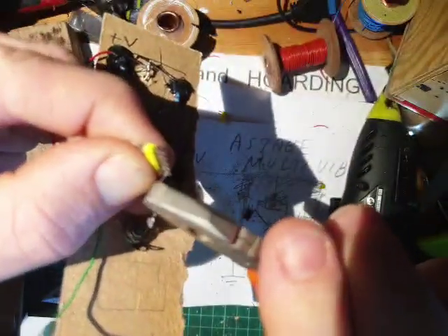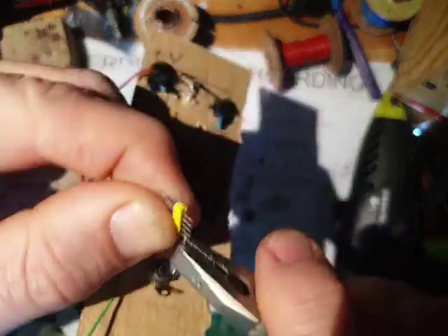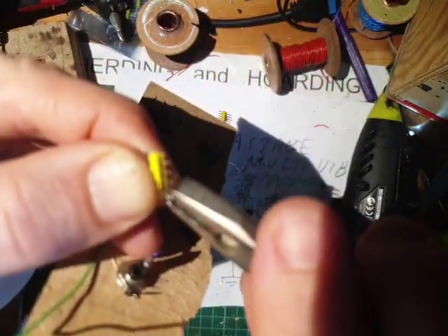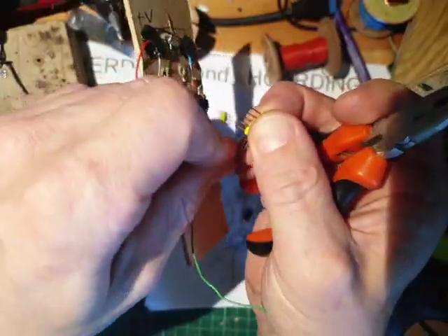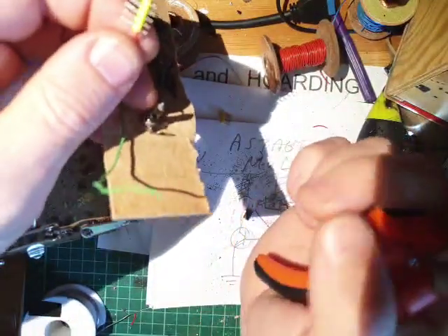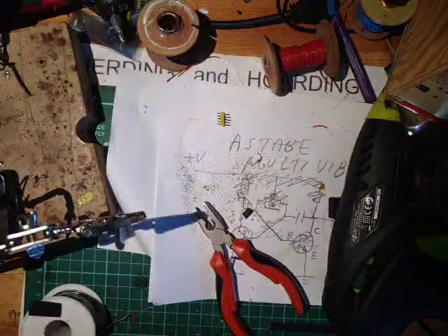Because in the Eurorack cable we have 6 wires for ground, 2 for positive voltage and 2 for negative voltage. This module only uses positive voltage and ground, so we could choose between using 8 wires or just 2, or as I am doing now, using 4.